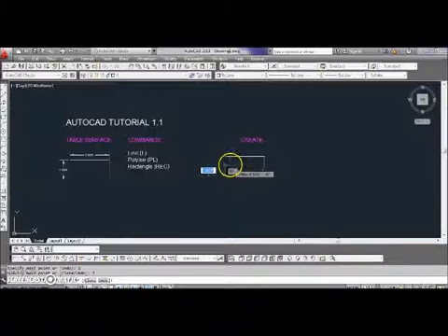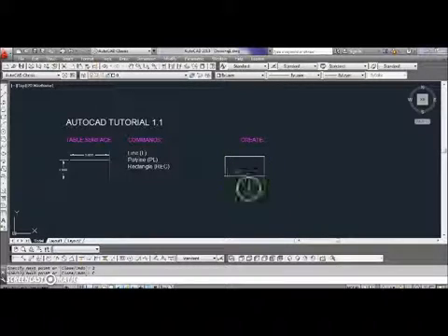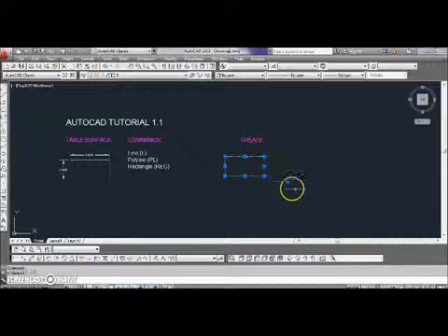And to close the line, I can click with the mouse, or I can use the letter C, that means close line, C, enter. And there you have it. We have our first element, our first table surface made with our command line. In this case, this table surface or this shape is created by 4 separate lines.